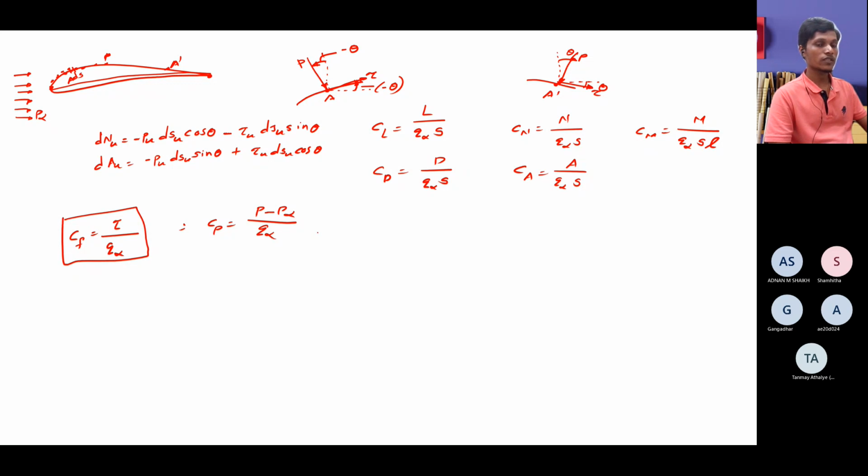Now let's go to the entire aircraft and see how the thrust acts. A very simple form of the thrust equation, the propulsion equation, is m dot times V_e, where m dot is the mass flow rate of fuel plus air from the jet engine.